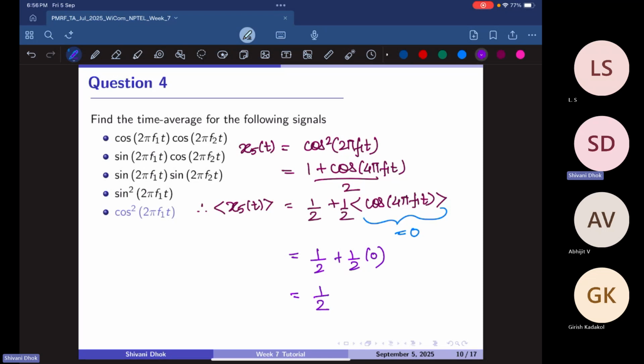So this is how you will be calculating the time averages when you have a product of sinusoids with different frequencies or the same frequency. Using these equations, you can now try out that derivation of your temporal correlation coefficient before mapping it to your Bessel function for your Jakes simulator.